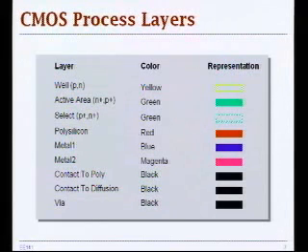And then in order to create connections between these different layers, you have these black boxes that basically make interconnection between your metal and poly and diffusion. That's represented with these black boxes. So you basically have an overlay of two materials, and then you have a hole that is filled with metal layer that connects the two.